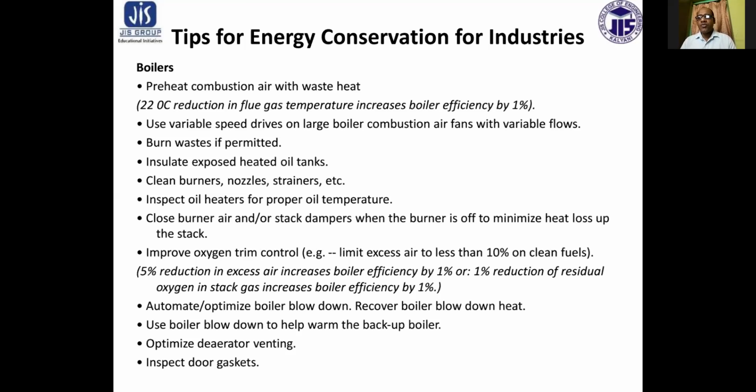Use boiler blowdown to help warm the backup boiler. Optimize deaerator venting. Inspect door gaskets. So these are all the possible areas where leakage may take place, that is, heat leakage may take place.